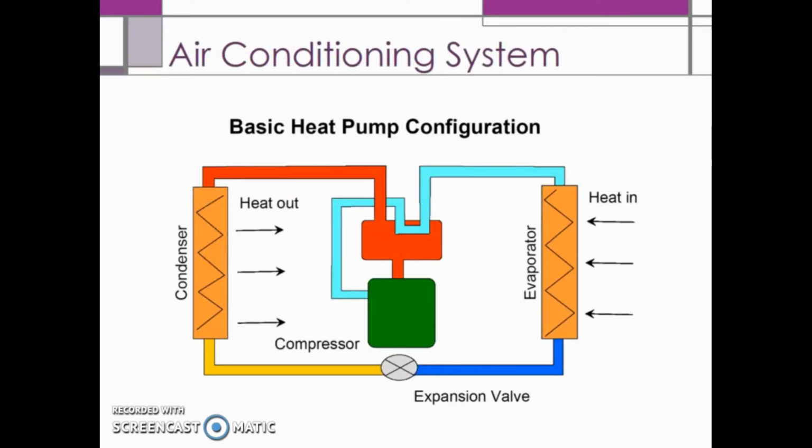The refrigerant comes into the compressor, or the green box in this picture, at low pressure, low temperature. The compressor performs work on the fluid, compressing it to high pressure and therefore high temperature. It is now a high temperature, high pressure gas. This hot refrigerant goes into the condenser, which is mounted on the front of your vehicle. It is mounted on the front to get fresh air because even on a really hot day, the gas is hotter than the air outside.